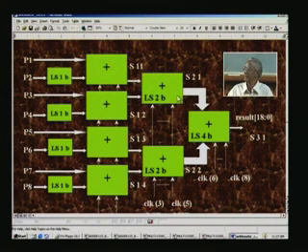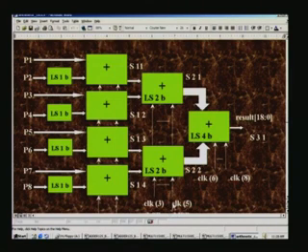Like this we will have 4 such results, and these two will add. This time, in the second stage of addition, we had to left shift by 2 bits. Why, we will explain in a minute. Similarly S13 and S14 are added up, and once again S14 is left shifted by 2 bits and then added up. Once again the LSB will be added first in clock 3, and there is one extra clock because the bit precision has increased internally, and it will be increasing progressively. So we want to give a little more cushion, and therefore we spend one more clock.